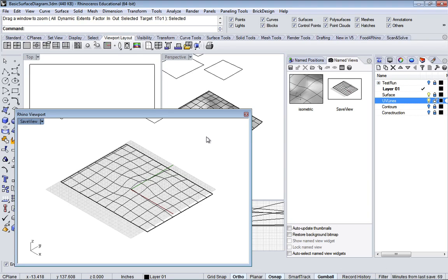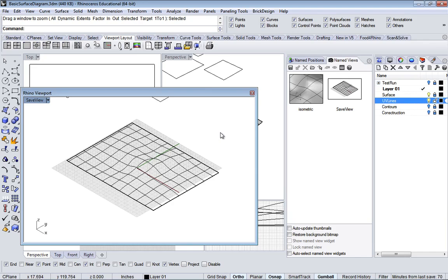Now, other tutorials you'll find online show ways of doing it, but then you have to scale it and you have to guess, and it's a bunch of guesswork, and it's a pain in the butt. So one of the reasons we selected a very specific size of 8.5 by 14 is because I know what that size is, and I can create a ratio. So it's a ratio of 8.5 to 14. What this allows me to do is create a viewport, okay, that is that 8.5 by 14.